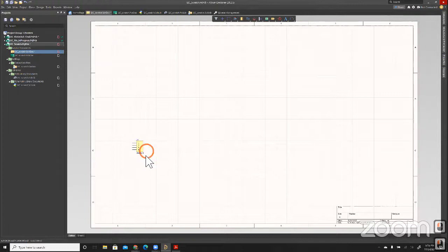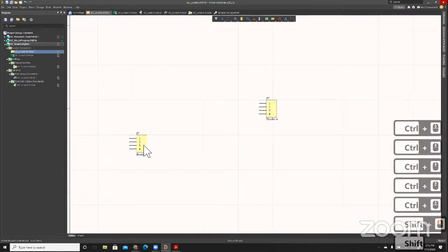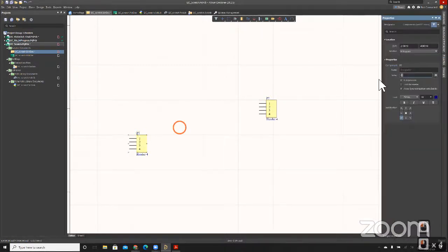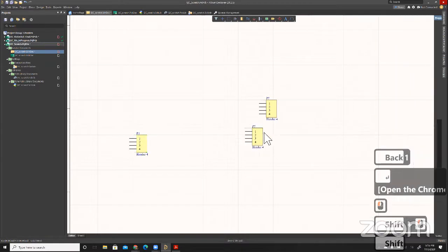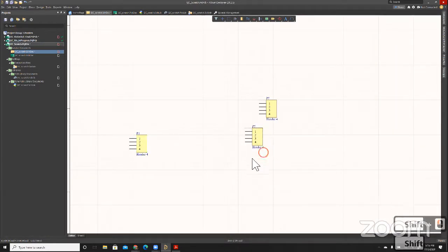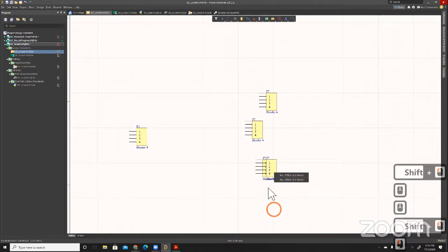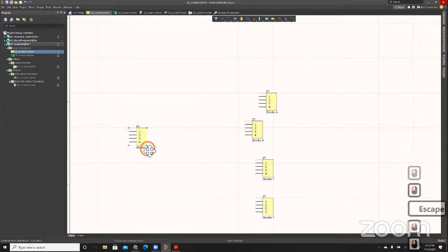And then a nice thing that can be useful in Altium is if you hit Shift and drag, you'll create duplicates of it. And I think actually even, so if I'm gonna show something else later, but if I name this P1, and then I shift click, oh, okay, it didn't do it that time. There's various ways that it will automatically change things. So I've got the 4-pin connector to the RoboRio, and then I've got 4 4-pin connectors for the JSTs.